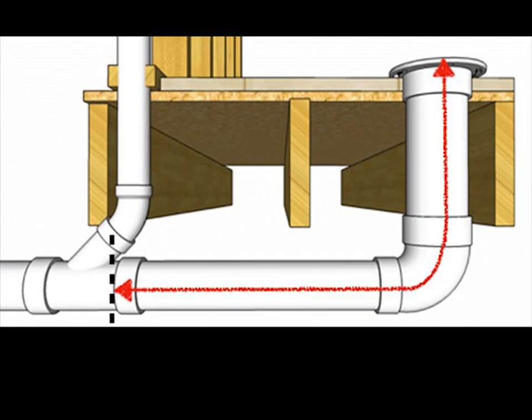Toilet placement in the bathroom. Toilets need to be set between joists. The drain is 12 inches from the wall, with 15 inches minimum required from sidewalls. The drain is 3-inch PVC DWV pipe with a 3.5-inch outer diameter.